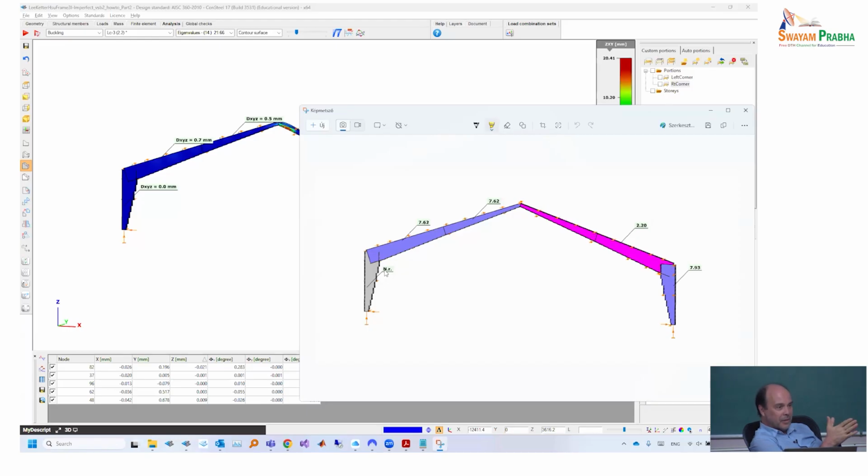The impact, if you would calculate with the load multiplier or critical load multiplier of 20, any sort of slenderness, would be so little that virtually it has no meaning from global buckling point of view. Actually, that's the reason why Eurocode suggests to look only up to 20 with the load multiplier. So you can force to have it calculated if you want, but probably it's just a waste of time, but as a learning curve, it makes sense. But practically, it means that there is no importance of that, even if it's calculated.